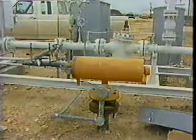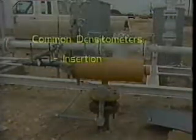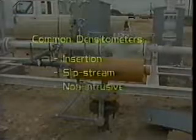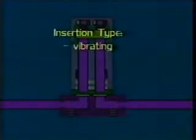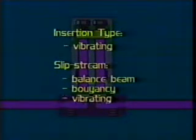There are basically 3 types of densitometers: the insertion or inline type, slipstream or strip sampler type, and the non-intrusive type. Densitometers can also be characterized by measurement method. All insertion densitometers are the vibrating type, while slipstream densitometers can be either balance beam, buoyancy, or the vibrating type.